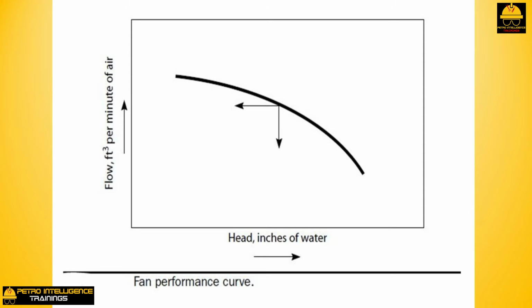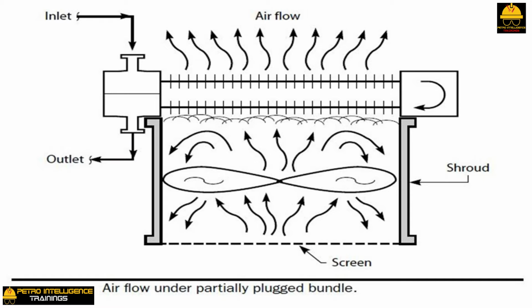Naturally, there is no reverse air flow on an induced draft fan. That can occur only in a forced draft fan. Reverse airflow can be observed with a forced draft fan by seeing which portions of the screen, shown in picture, will not allow a dollar bill to stick to the underside of the screen.